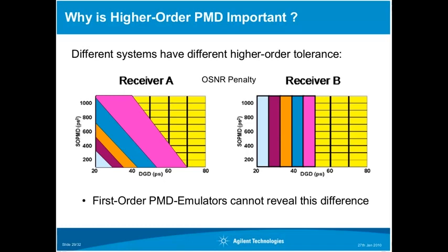And interestingly, the 100 gigabit receivers have a lot of influence on this kind of behavior because most of the receiver properties are coming from some sort of FPGA or ASIC software. So now moving to 100 gigabit, you really have a handle on optimizing your receiver with respect to PMD tolerance. So I think this is a thrilling point here, that you really can use these test and measurement approaches to optimize your receiver with respect to all these parameters.